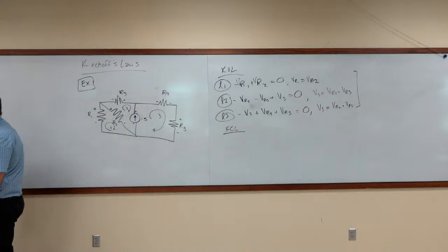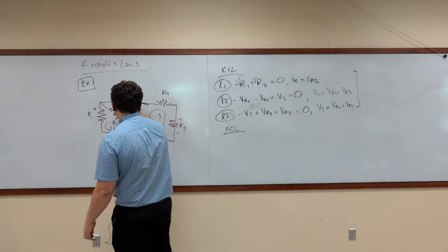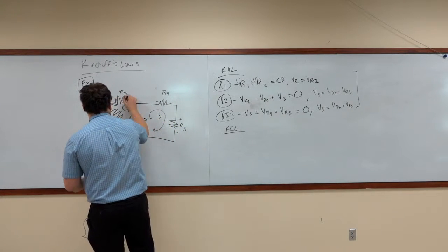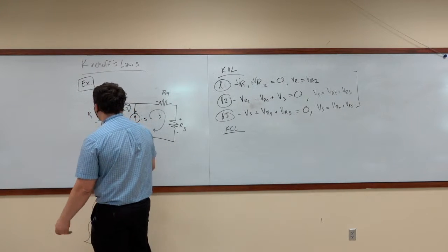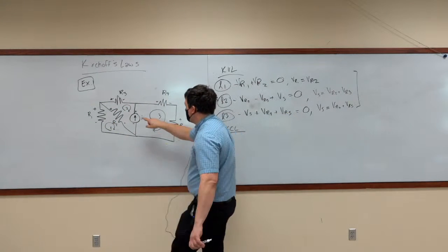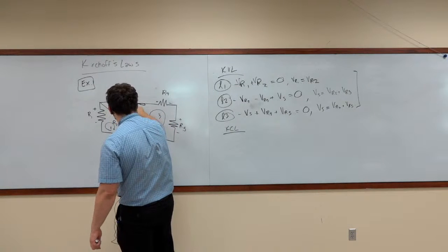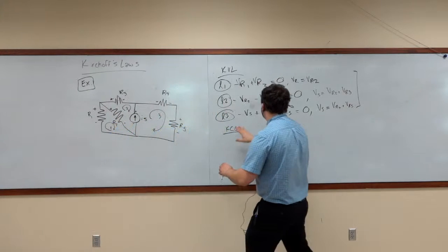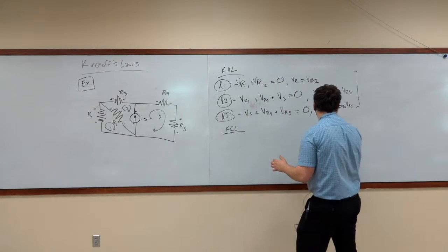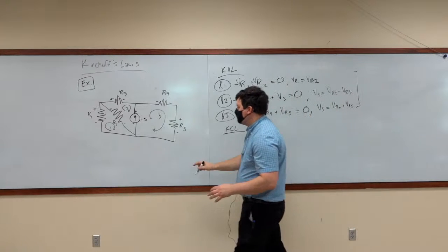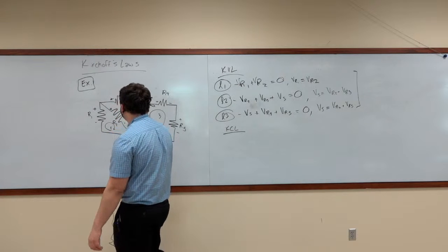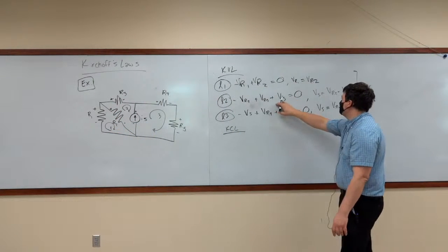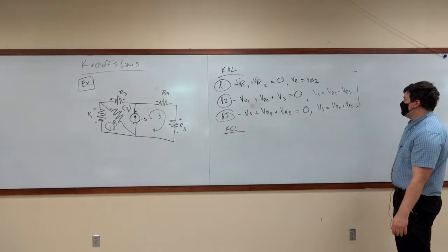Now, yeah. So if we get like VS equals VR2 minus VR3, then we wrote VR3 backwards? Probably, yeah. And what you would see here is let's take R3 and just flip it around here. Okay? We'll say that we accidentally wrote it backwards. What you'd end up with here is, as we go around, this would come in as a negative component, this would come in as a negative component, this is a positive, that's a negative. So what you would see here is this would switch, and then we would end up with this negative sign here. And then, yeah, nothing else touches R3, so you would just end up with this one negative, and that would just tell you, like, okay, if you get a value for that, it's probably not negative.